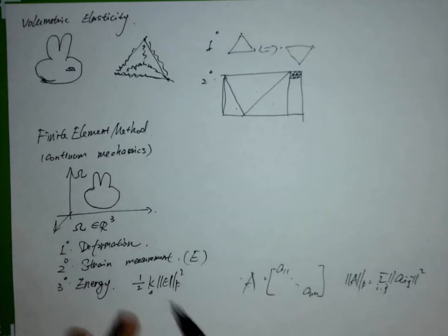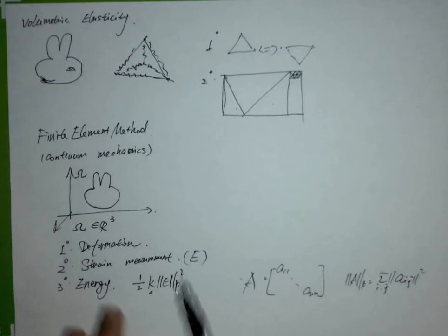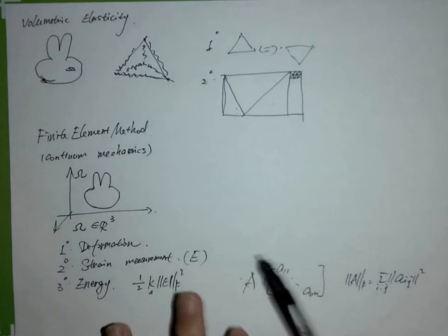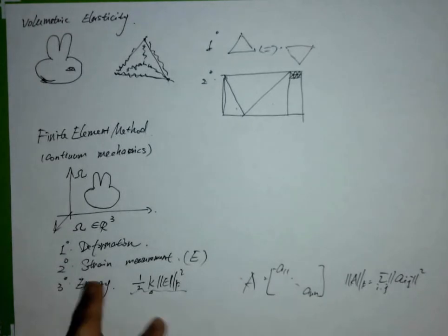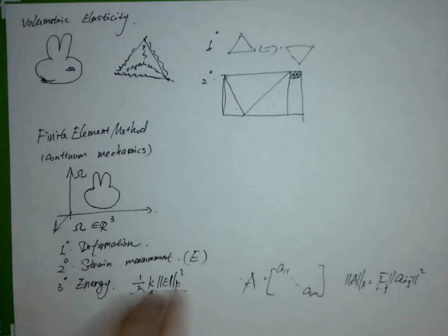This is a sort of naive model. If I have a strain measurement to measure how my current deformation is different from my rest pose, the really straightforward way is to get the energy like this. It looks pretty much like your mass spring system, all right? Because if we want to measure how much my current spring is different from the rest pose, I just measure the current length of the spring minus the rest length of the spring, and then we basically take the square of it, and this is our energy.